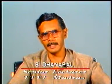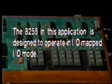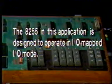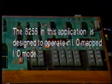But how do we load the control word? The application is designed to operate in I/O mapped I/O mode. Therefore, the out instruction can be used to load the control word into the control register. Let us now move on to the graphics to learn about the steps in programming the device. The 8255 in this application is designed to operate in I/O mapped I/O mode. The I/O address of the control word register is 23H.